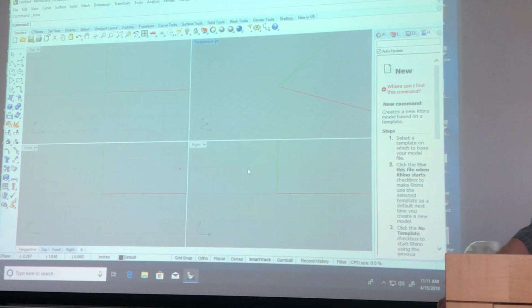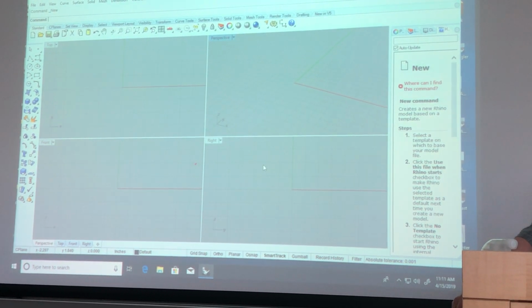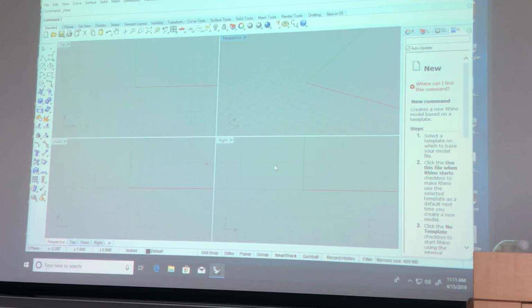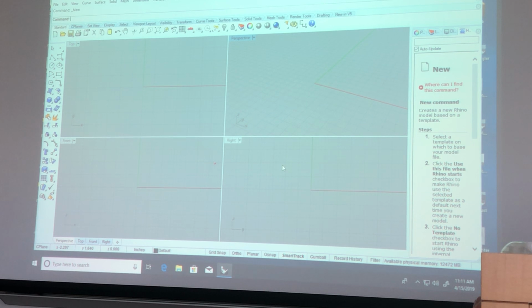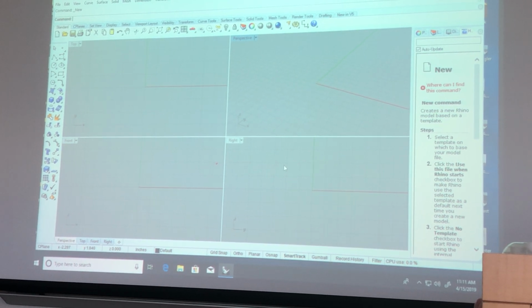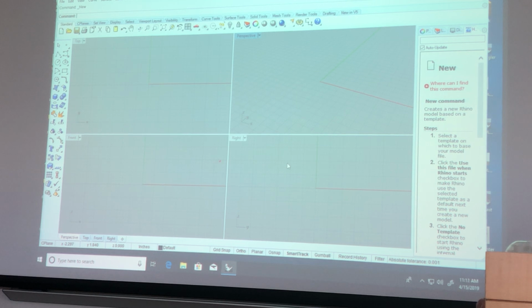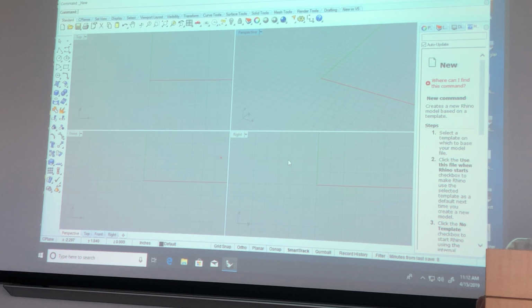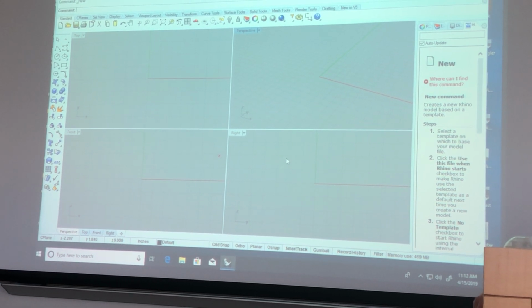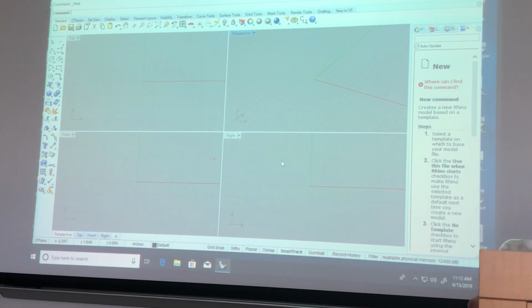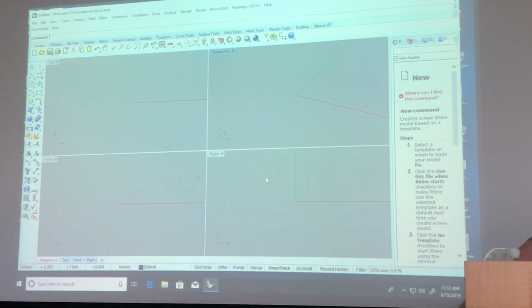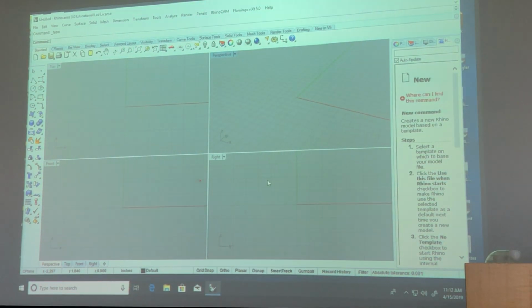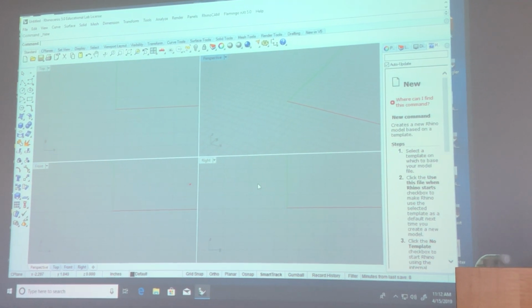I'm going to ask you a math question you're not going to want to hear. Hey, what's 6 inches if your scale is 1/16 of an inch equals 1 foot? If in your real model your wall is 6 inches thick, how thick is it going to be at your output scale? Less than 0.0. Less than 0.5. See, so you've got to work on this math.